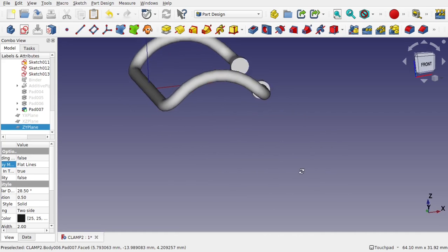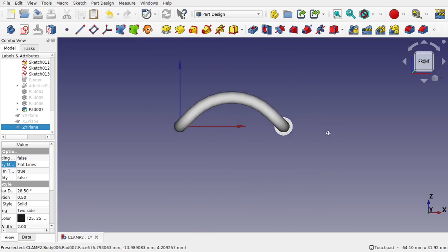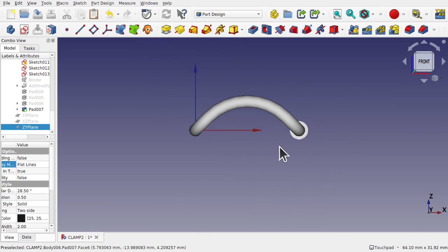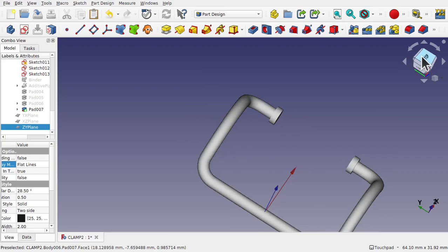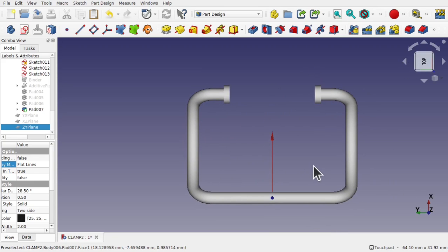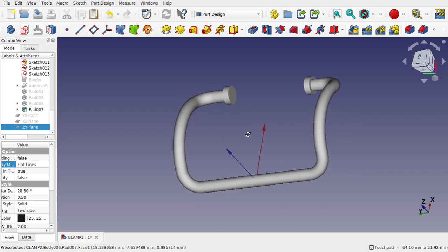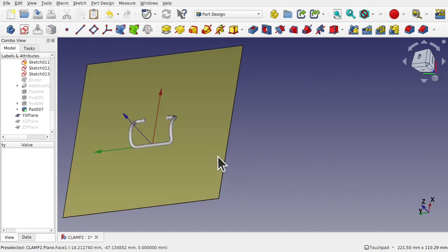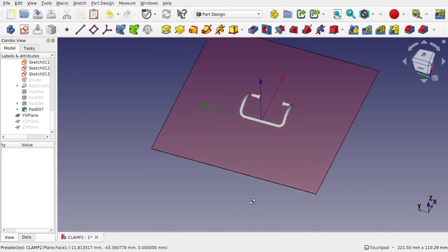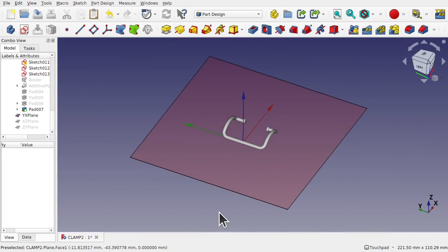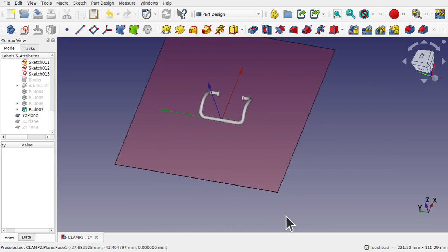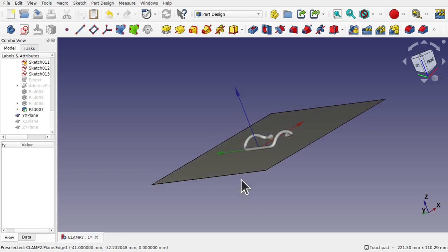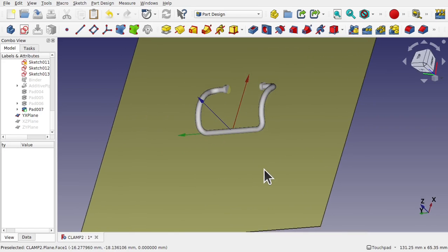If we look at the profiles from the front, we can't model the whole object from the front because we have this curvature that goes along here. If we look from the top, we can't model it from the top either, because if we look at the profiles, we're looking at the planes and how many points lie on that plane. So we've just sketched out the planes upon this. We can see how that sits flat on that plane at these points here. But we can't sketch upon that plane because this is curved. This curves upwards. So sketching this as one object is not possible.